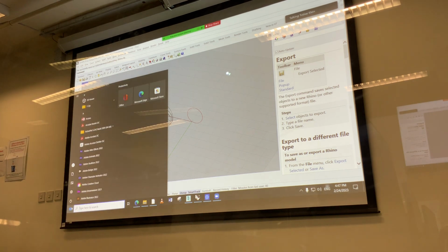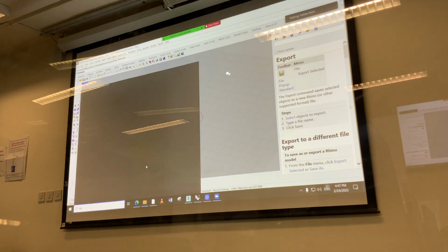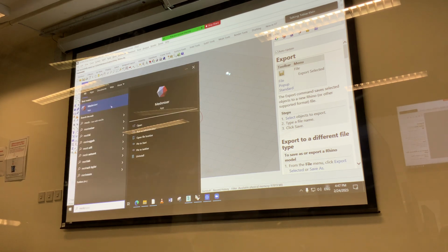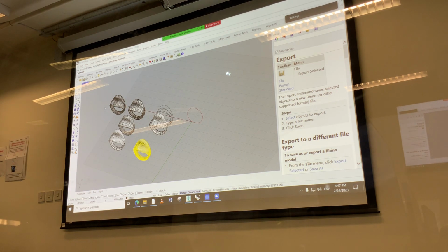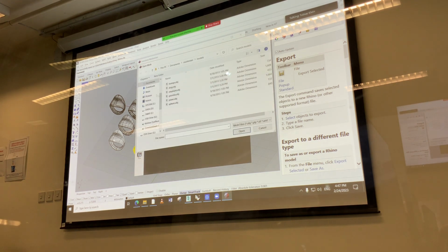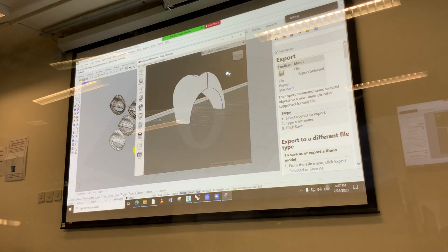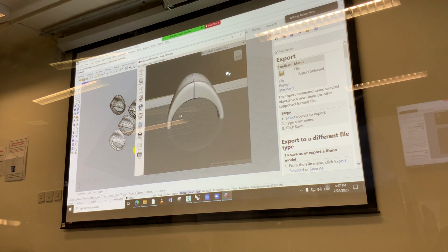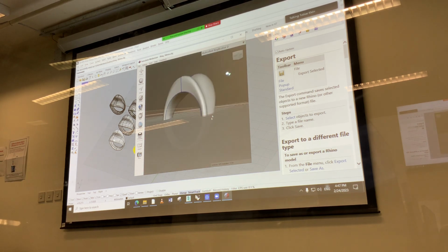So okay, basically. Let's look at this ring now, for instance, in Meshmixer first. Just to check it out. So we import now our ring. Here it is. We click on the shader and we push a shading material onto it. And you see this blue thing means it's open. So that's bad, really bad.